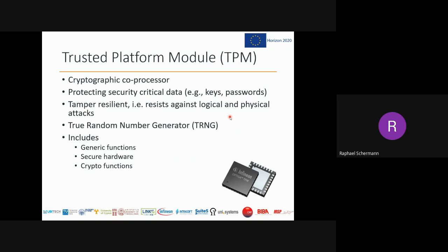Now, I will give you an introduction to the Trusted Platform Module. A Trusted Platform Module is a separate cryptographic coprocessor that is attached to the host platform where the operating system is running. It is commonly connected over an SPI interface, and it is used to protect security-critical data. Such security-critical data are, for example, keys or passwords, and it is also TCG compliant,